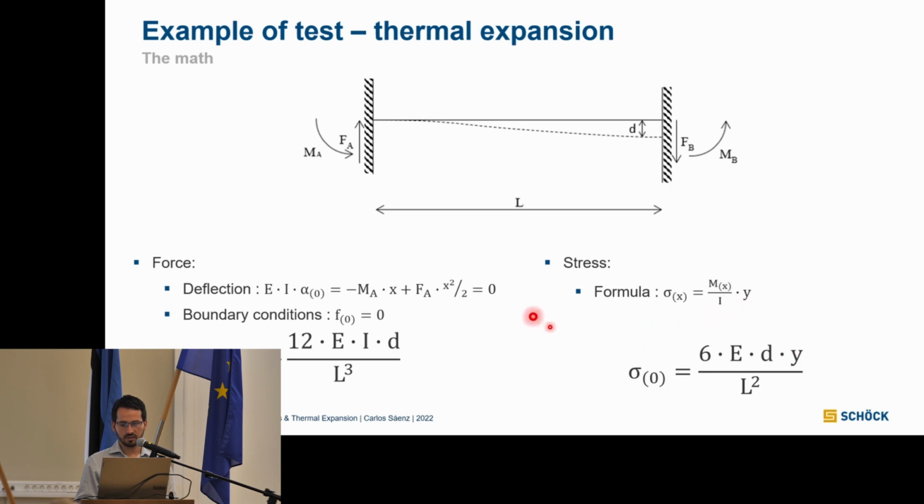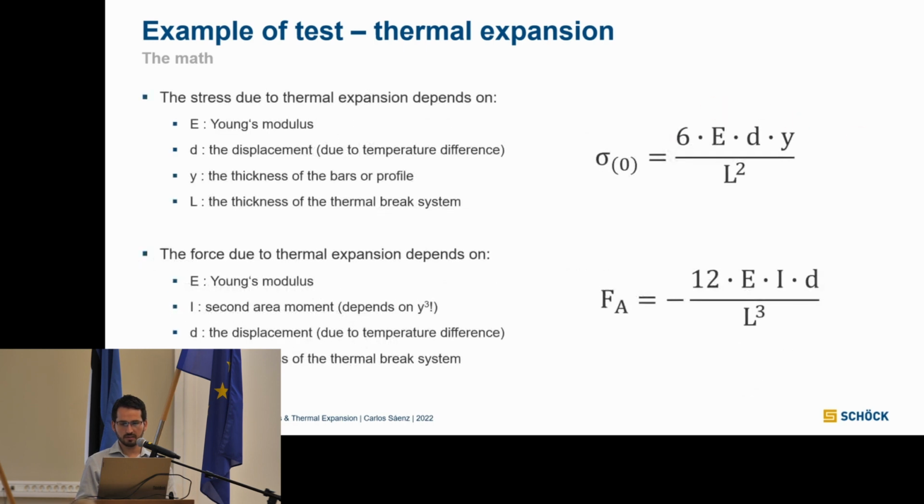On each side you get to see we have the forces because we have an equilibrium. But the important thing here, if we take a closer look at the values, is that it depends a lot on the Young's modulus, and on the area, which is related to the size of the system and the thickness of the thermal break system. Because when you develop your thermal break, you want the stress to be as low as possible.